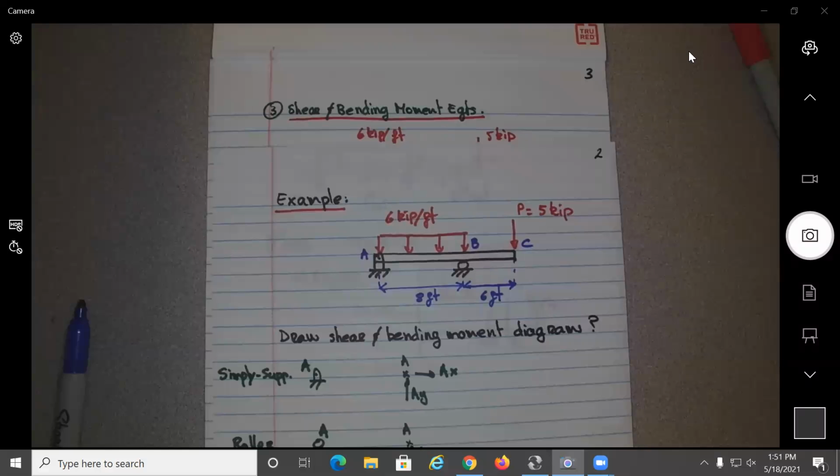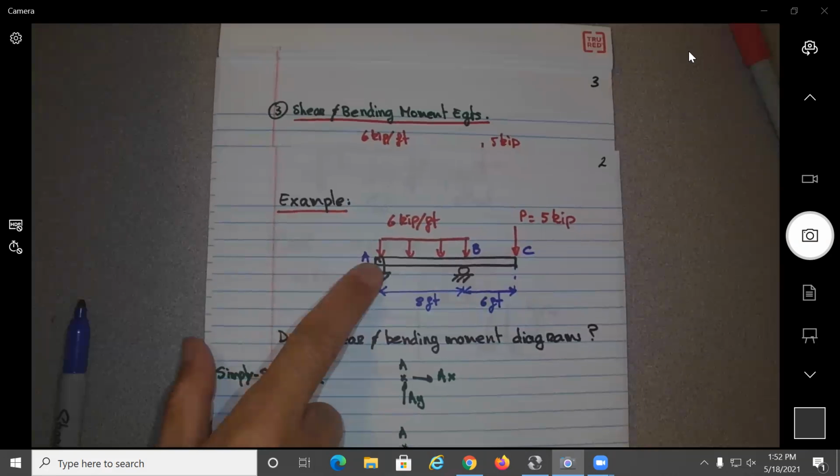All right, because the internal actions, shear and bending moments, those are internal actions, okay, within the structure. And you know that by Newton's third law, every action has an opposite reaction. Okay, so if you don't make a cut, it's like here. Why do we remove the support? We remove the support A and we replace it by two forces, no? Because if you leave the support, the support is going to counter-react the force of the beam, no?